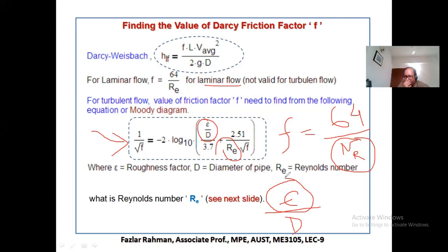So normally in Bangladesh, what we do is go to the store and buy a pump, right? But if you work in an industry, a multinational company or a Western country, they will not buy immediately. They will ask the manufacturer what the roughness factor of the pipe is, or the company might show you in their website or in their specification. So obviously you will buy where surface roughness is very low, right? Otherwise your loss will be high.